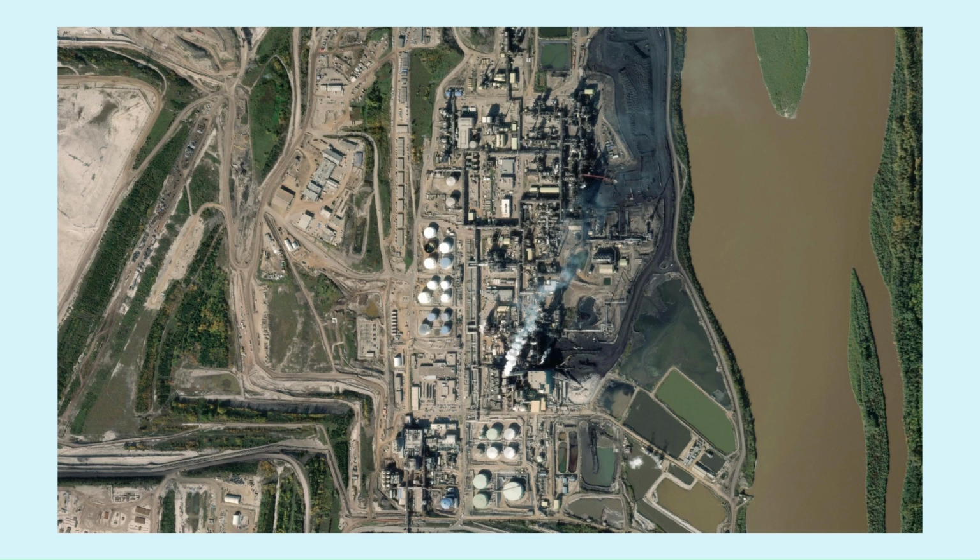Imagine if you had to account for that 30-ish degree rotation off north in every single one of your calculations as you're trying to lay this out. Didn't make a lot of sense. So that's why we created those plant grids in the past. And even now, with the computers and everything that we have, that scale factor is still necessary so that a unit of measurement in the grid matches a unit of measurement on the ground.